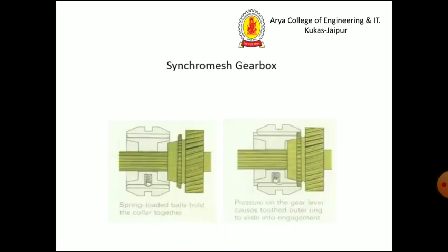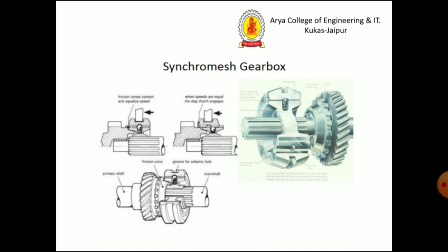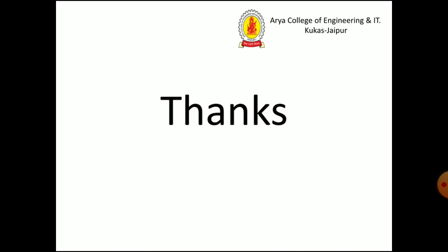This is the general construction of the synchro mesh gearbox, in which spring loaded balls hold the collar together and pressure on the gear lever causes the tooth outer ring to slide into engagement and the power may be transmitted. This is the constructional detail of the synchro mesh gearbox.